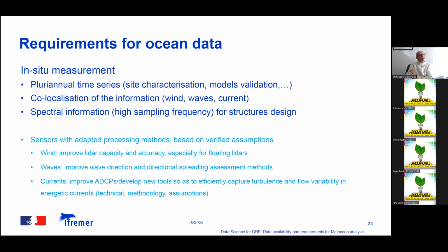Regarding in situ measurement, what we need are at least a pluriannual time series for site characterization and also for models validation. This information should be co-localized and also provide wind, waves, and currents together, and also high sampling frequency for spectral information. For in situ measurement for both wind, waves, and currents, we could improve sensors and measurement capacity, also processing methods for these sensors.